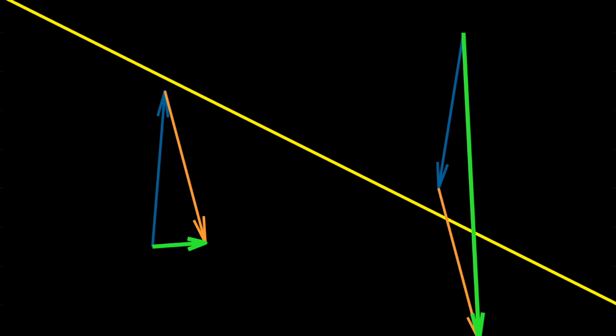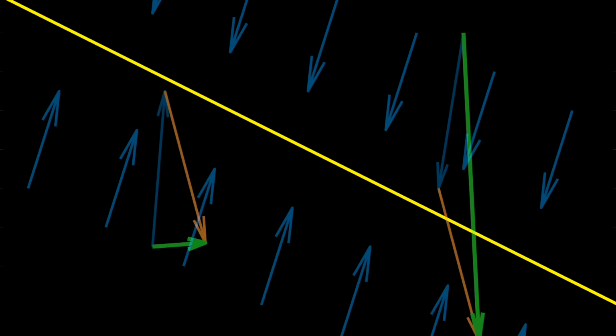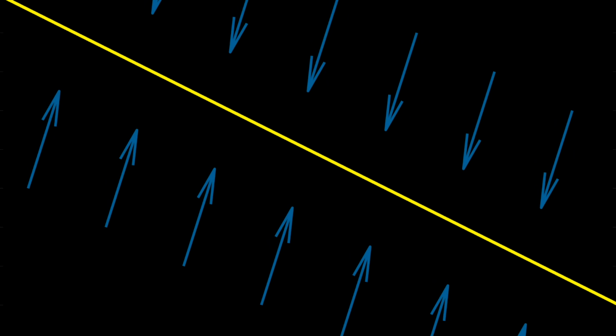Effectively, what we're doing here is using very high gain and switching back and forth between two different controllers to make sure that the system stays along the sliding surface. And with that high gain, we get the benefit of not being susceptible to system uncertainties and external disturbances, because the high gains will just overpower them, which is great for robustness.